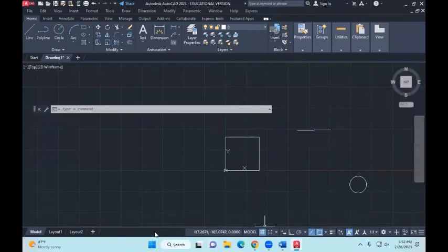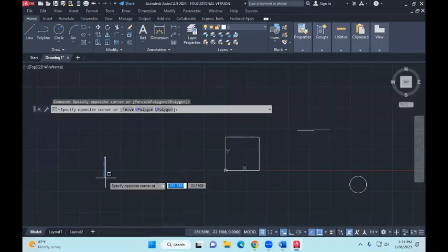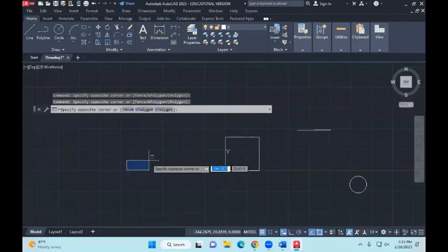Now you'll see right at the bottom is your status bar, right? The status bar has a lot of buttons at the bottom. My first one is coordinates, next is model. There's this grid, and where it says dynamic UCS, there, this one. If you hover the mouse over it, you'll see dynamic input. I'll show you the difference. If dynamic input is on, you see what happens? If I click beside the crosshair,